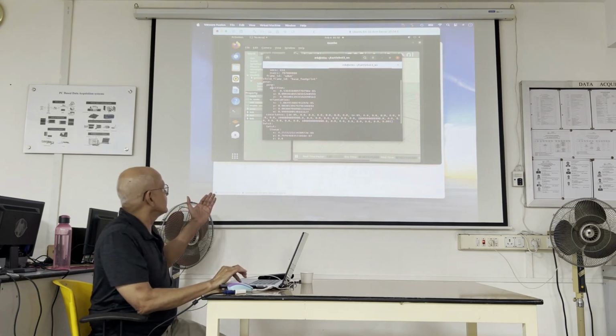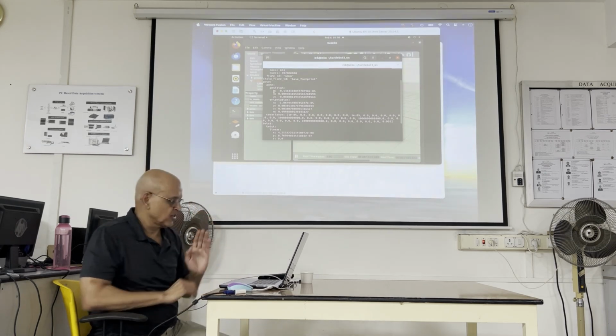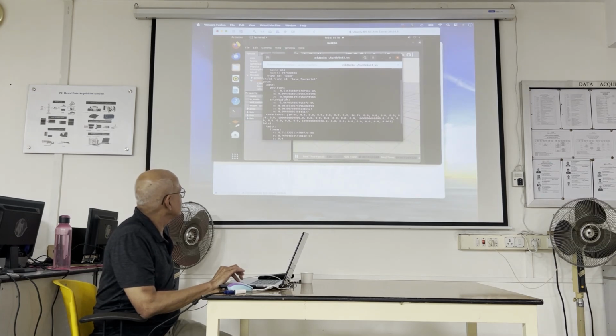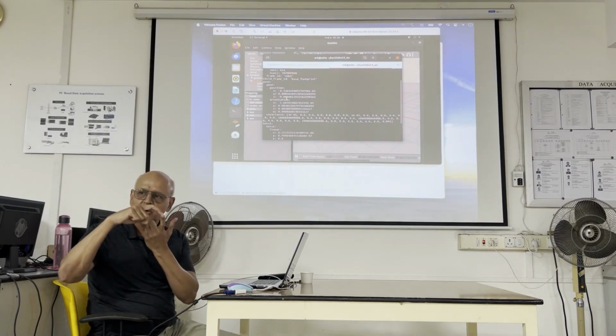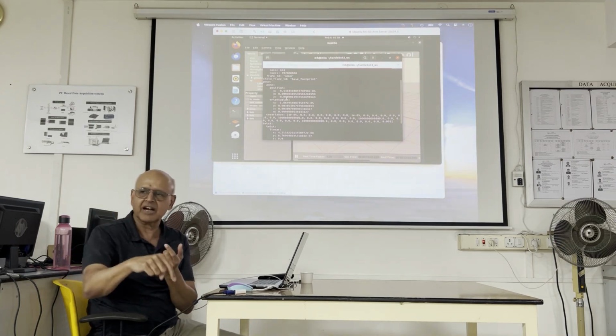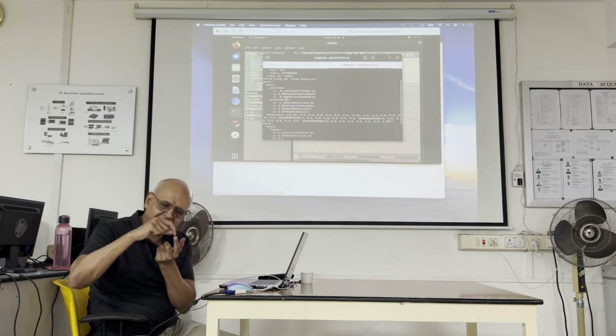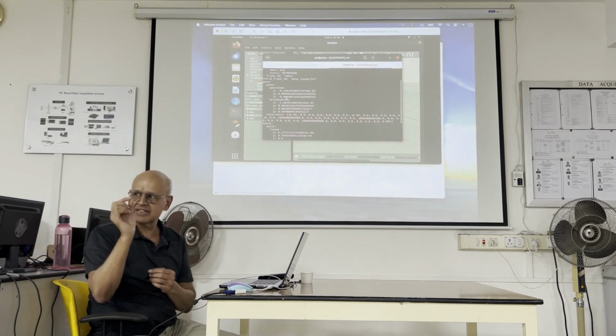But it's designed to report Z because you can also run drones in Gazebo. So it's reporting Z, and notice it's a very small value because the center of the robot whose pose is being reported is not on the ground. It's slightly above the ground, because the wheels are there. So the robot center is slightly above ground.